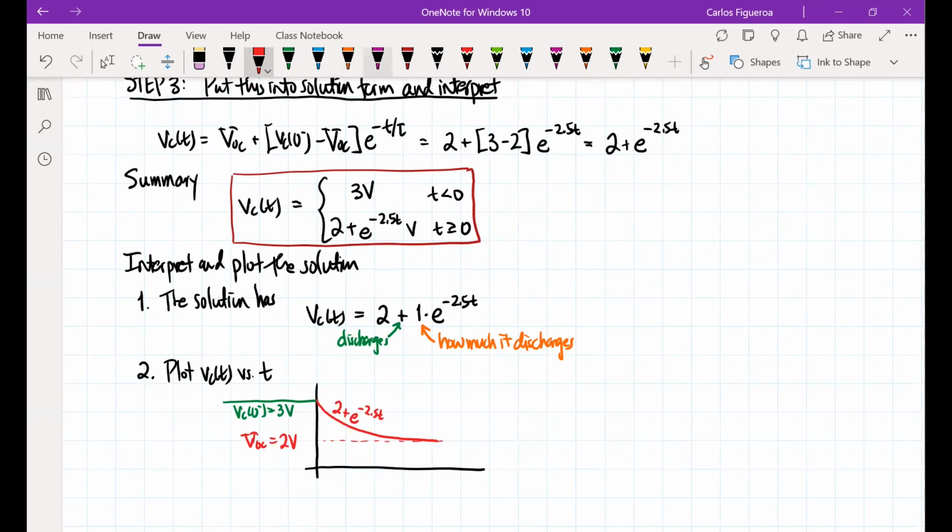Now, look at the discharge voltage. If I look at this right here, you can see that the drop from here to here is a voltage drop of 1 volt. And look at that 1 right there. So this is exactly what we'd be seeing here.